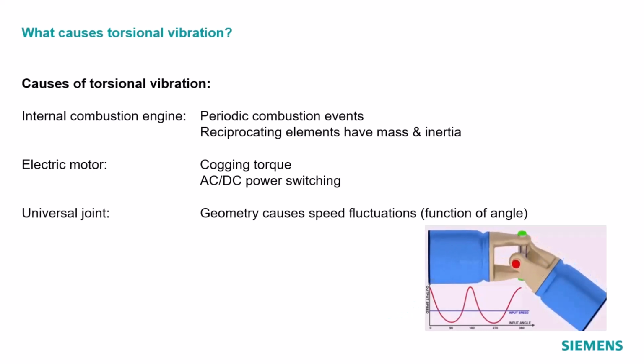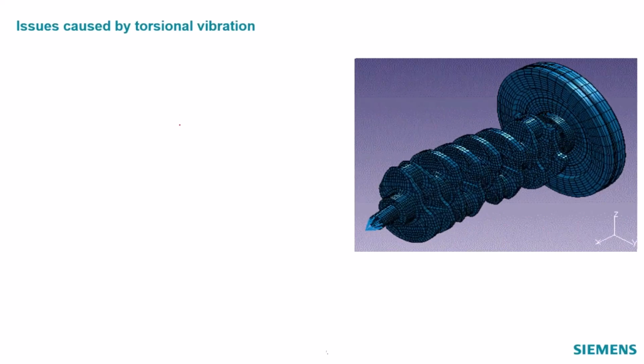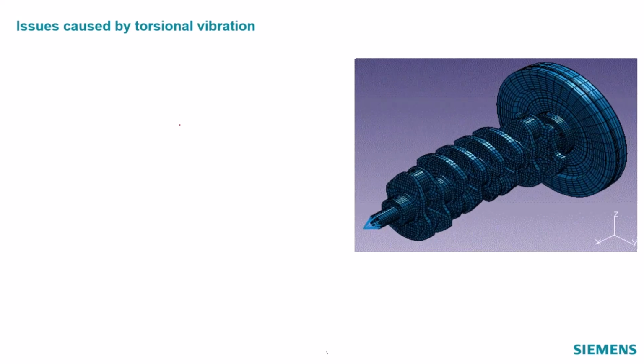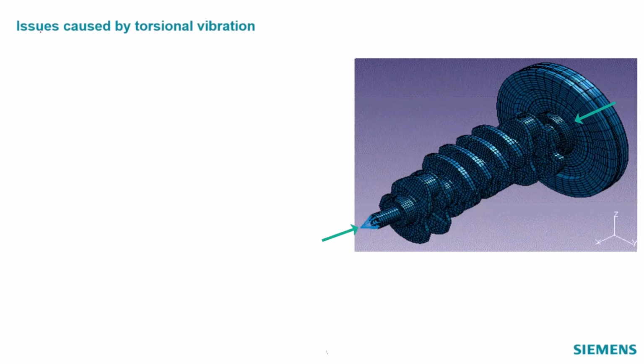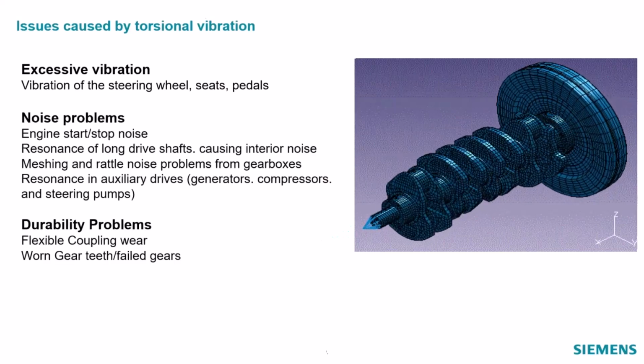Yeah, there's just all sorts of things that can cause the RPM of something to fluctuate. And I guess this is even potentially another cause. If you have a shaft, it's also possible the shaft has a natural frequency or resonance where it twists from one side here to the other side. There's going to be a delay in the RPM. So it's a bunch of fluctuations. And these RPM fluctuations cause all sorts of things.